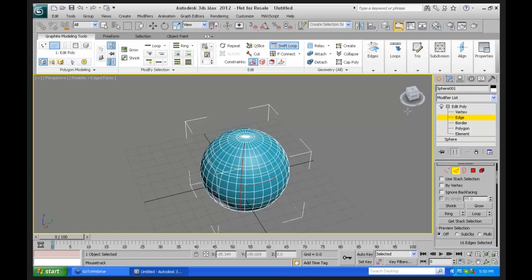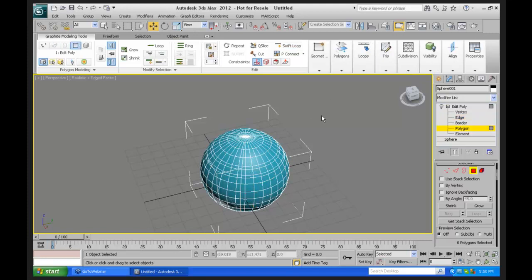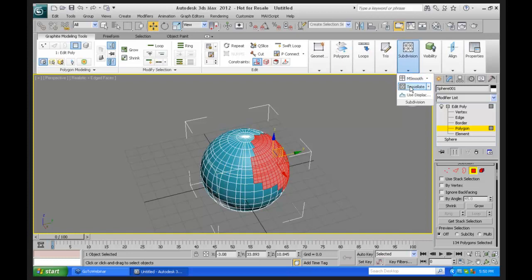What you'd have to do would be to add a tessellation. As far as I know, you'd have to add a tessellation at that spot so that you can tessellate at the object level. So I'll come over here and say, okay, I want to select those faces, and then I go tessellate. You'd have to do it manually like that, I believe.